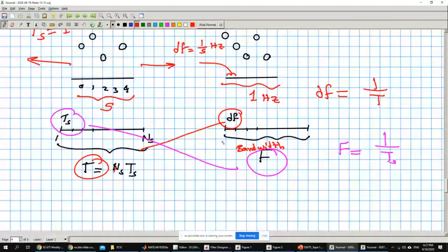Again, the step in the frequency domain between the samples is df. If I have a frequency like 10 Hertz and want to know how many points are within 10 Hertz, I divide 10 Hertz over df. This will give me exactly how many points I should remove.